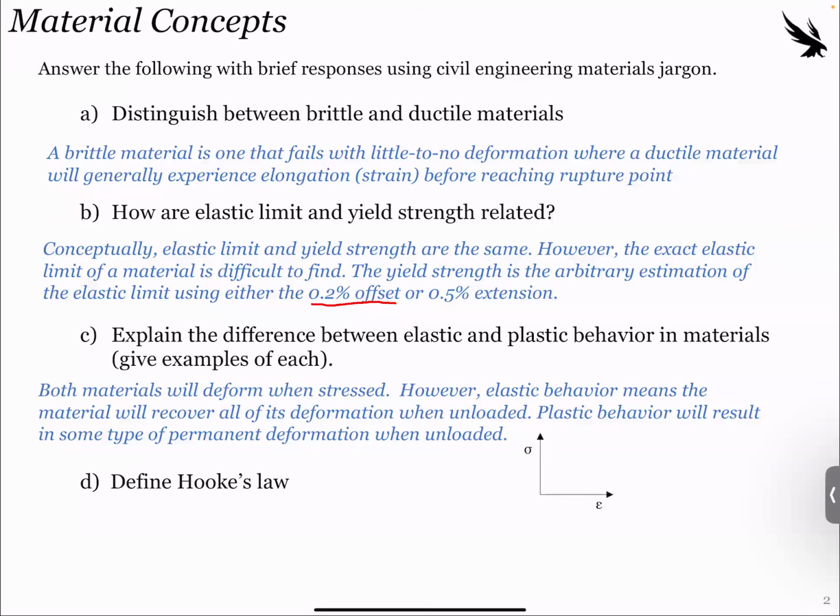So just graphically, if we had stress versus strain here, for elastic behavior, we load and unload, and it goes back to that zero point shown here, zero stress, zero deformation. If we had plastic behavior, when we load and unload, although we're on the y equals 0 line, so no stress, we still have some permanent deformation or permanent strain that's captured there.